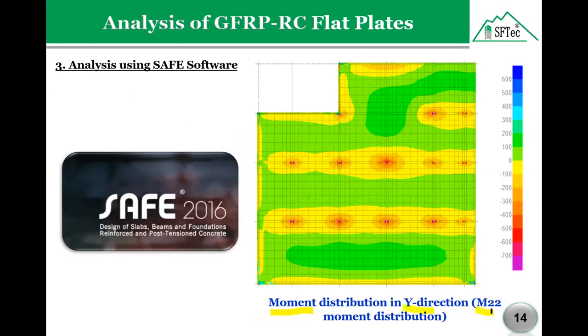In the program you will see the term M22. So here, as before, we have a color, and this color is the most common one here in the flooring slabs, and this is also for the positive moment. So here the positive moment is ranging also from 0 to 100. So it seems that we are going to have a uniform mesh in both directions. So we are going to take M ultimate positive for the uniform mesh to be 100 kilonewton meter.